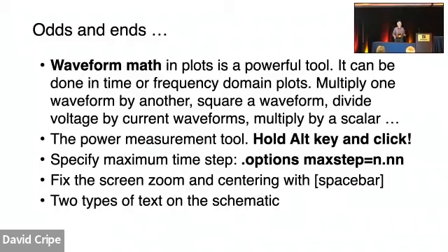So I thought, what about the 0.99? I changed the 0.99 coupling to 1.0 and ran it. Now I got 0.5 volts out as expected. So the lesson to me was there's a difference between 0.99 and 1.0. That's something you might want to keep in mind. Maybe you know how tightly coupled your windings are. It doesn't have to be one or the other. Maybe it's 0.995. So that's something you can fine tune. Okay, now I'm ready to move on from that one.